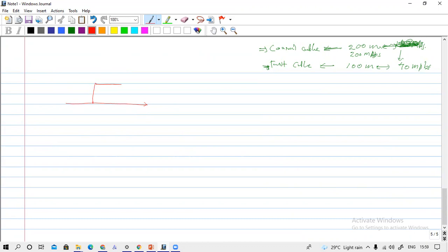Basically, if I tell it again, what you should know is, if we have a rectangular pulse from plus tau to minus tau, we will have this kind of spectrum. This will be pi by tau, this will be plus pi and minus pi by tau, and this will be 2 pi by tau like this. It is better to remember this, because this property we always have to use.